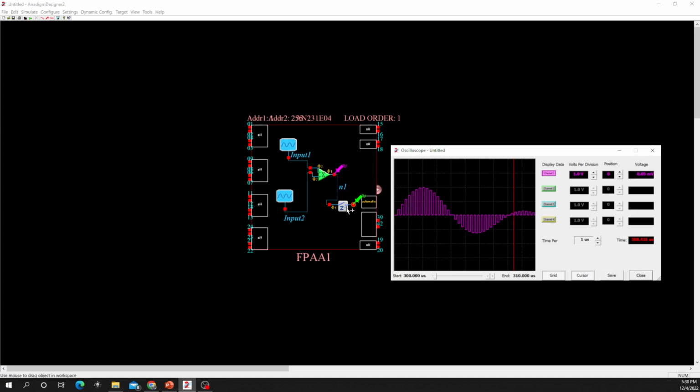The sample and hold one is working continuously in both phases. Let's turn the sample and hold one on and compare them at the same time. If you look at the sample and hold one, you see it is very continuous, right? But since they are doing the sample and hold, it will give you some delay. Let's zoom in even more. You see there is a clear delay. You see the sample and hold result is 1.64 volts, and maybe half a cycle before there is another 1.64 volts. So that's, I would say, reasonable.